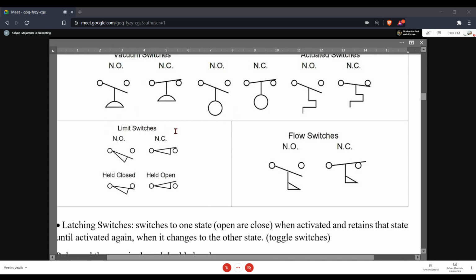You've seen this in your house. You've seen this at multiple places. Where have you seen this in your house? If you remember your fridge or refrigerator, if you open the door, the light turns on. You do not press any switch for the light to turn on. It happens automatically when the door is opened. And when you close the door, the light goes off. Again, that is automatic. That means there is some sensor inside which is sensing position. Position of what? The position of the door of that particular refrigerator. If the door is open, the light inside that particular circuit is closed, the light comes on. And if the door is closed, the circuit is broken, the light turns off.